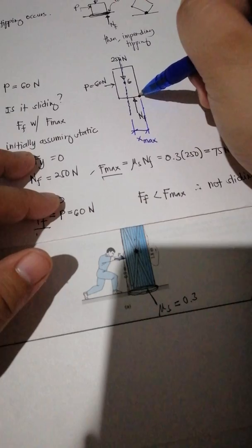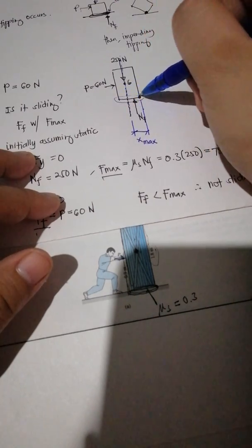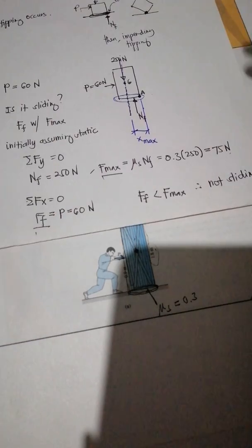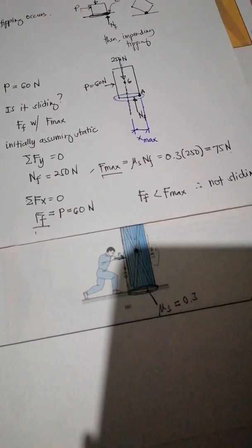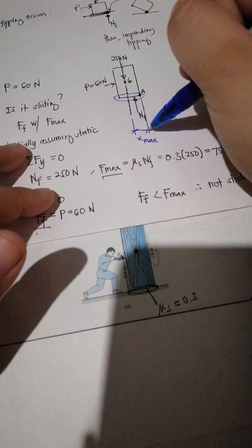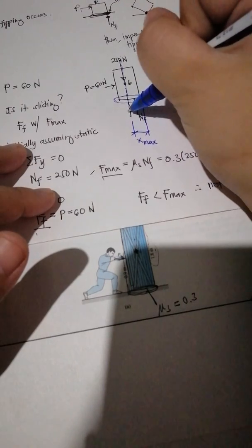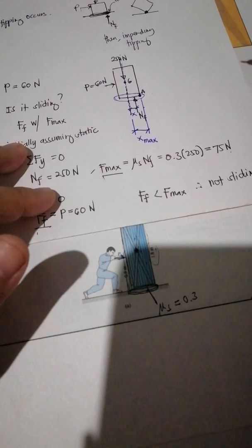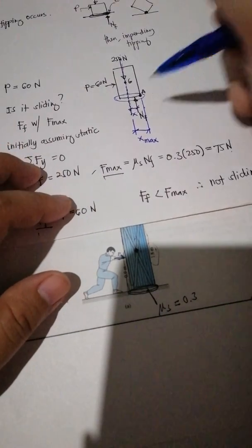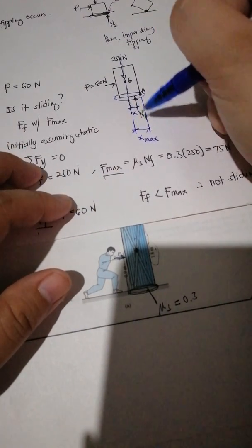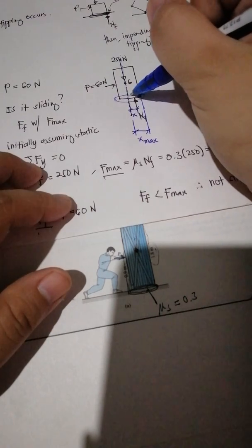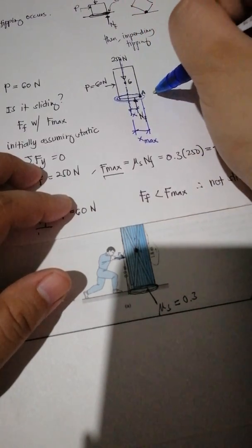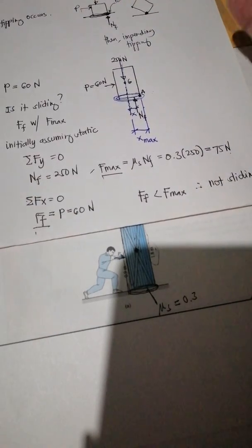But if it's within the plane of contact, not beyond the corner of tipping, then it's not tipping. The measurement of X is from the center of gravity to N. If X is less than X max, meaning the normal force is only acting within the contact area, not beyond the tipping corner, so it's still not tipping.